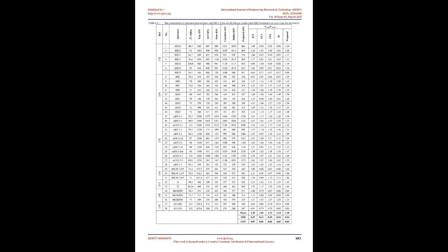It should be illustrated that in the proposed equation, the critical section was assumed to be at a distance of D/2 from the column face because this value has been used to define the critical section in the ACI code since the 1960s. Therefore, the critical perimeter, B0, is equal to 4(C plus D) for square columns and π(C plus D) for circular columns.